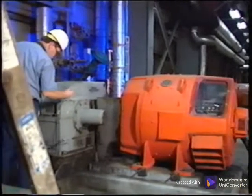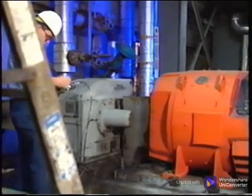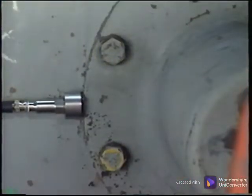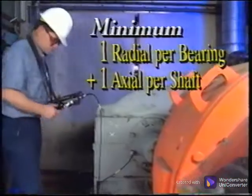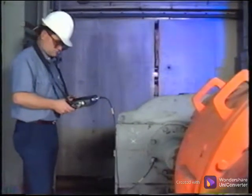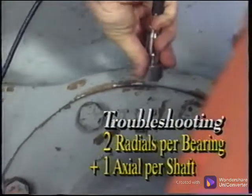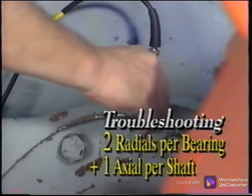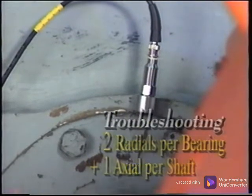Although the next video program in this series discusses gearboxes in depth, here we will cover the best measurement locations for them. Gearboxes have high-frequency occurrences that require exceptional data collection for proper analysis. Routine surveys for single reduction parallel shaft gearboxes require a minimum of 1 radial and 1 axial measurement at each bearing location. Use 2 radial measurements when troubleshooting problems in a gearbox. The extremely high frequencies associated with gearboxes may necessitate 2 measurements being made for each sensor location.